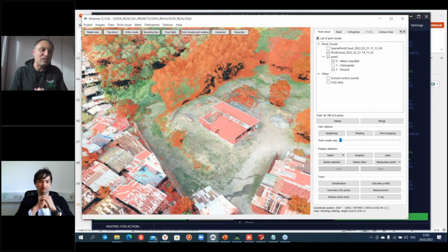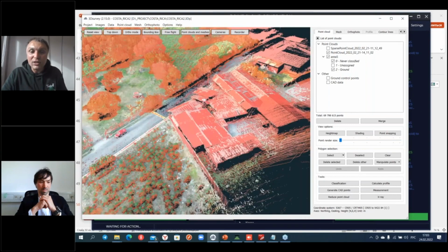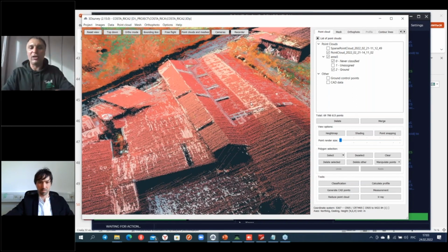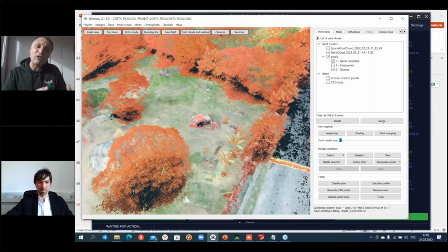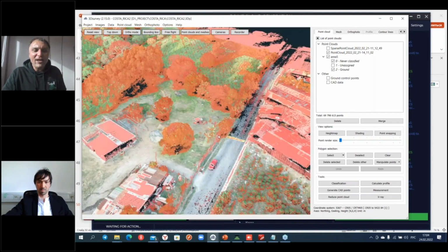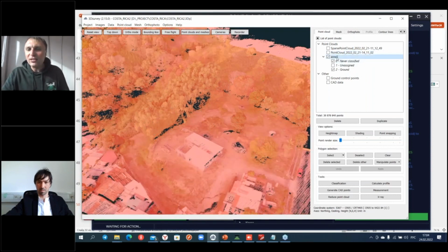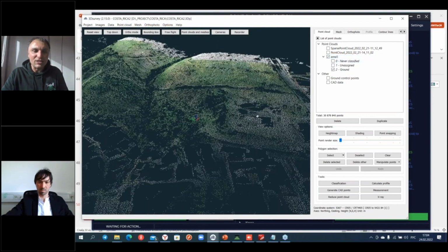It has very precise photogrammetric point cloud calculation. After that, you can add your LiDAR data like this one, and you can see that the LiDAR data totally overlaps the photogrammetric data, and all of them are aligned together without any problems. And of course, I don't do any correction in coordinates. It is due to the very precise post-processing and very precise aerial triangulation. Finally, I just switched off the point cloud from photogrammetry. After that, I switched on the LiDAR point cloud. After that, I will remove all trees and so on.